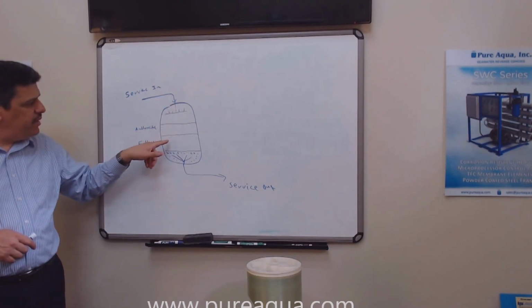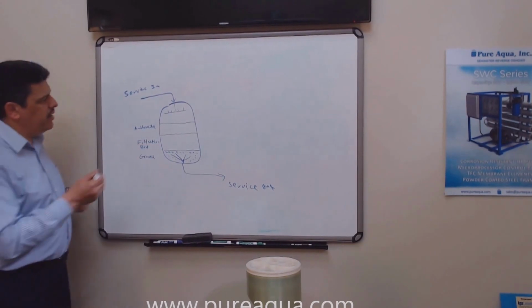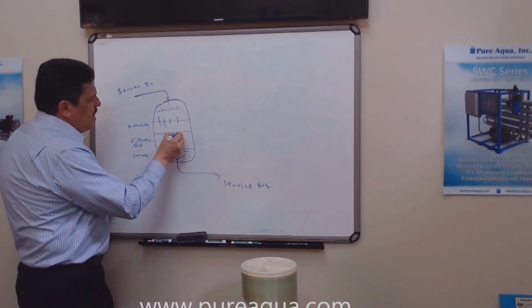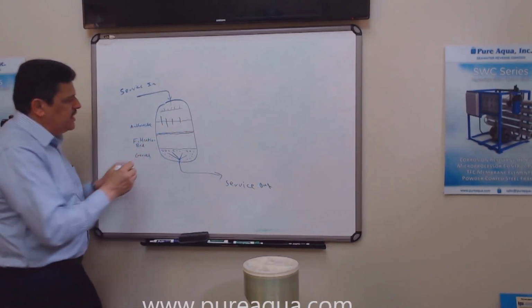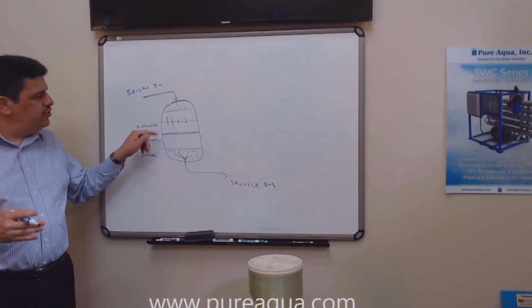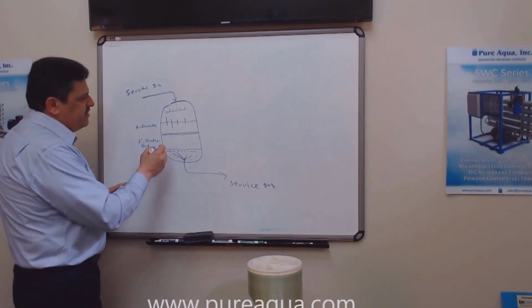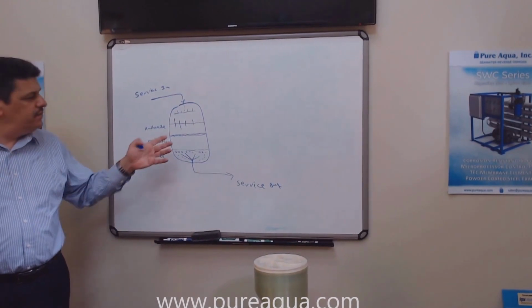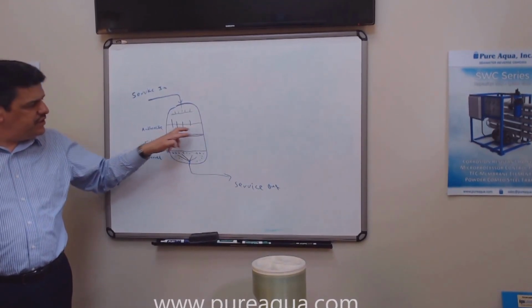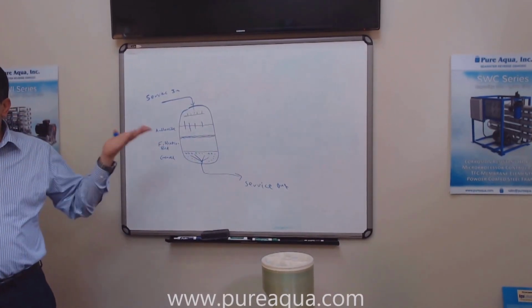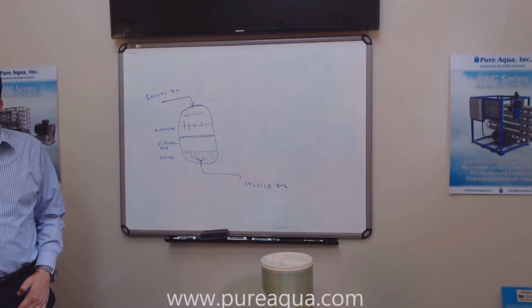It doesn't get hit by the filtration bed. Usually when the water comes here, it starts penetrating here, isn't it? So that's the upper layer of the filtration bed. That's what takes the most load, the dirt load. So let's assume this filtration bed is at about 30% of its life before we do the backwash. So you can have some turbidity or suspended solids here. We stop the filter because customers are using it or whatever.